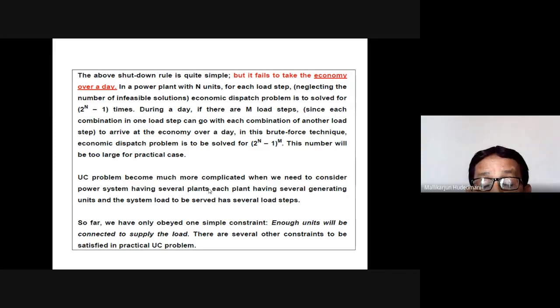That is used first. When the load increases further, another machine, second by priority, is combined. When the load increases beyond the capacity of the first and second choices, then the remaining machine, third or fourth, whichever is effective, is combined.